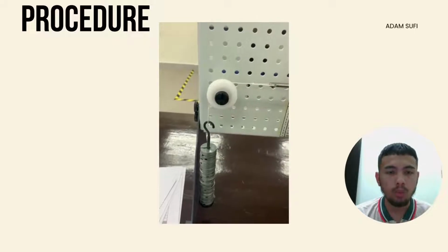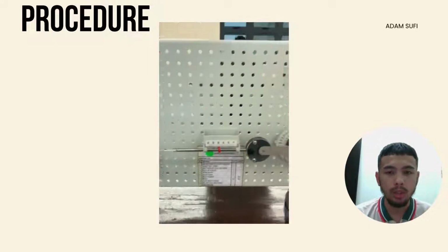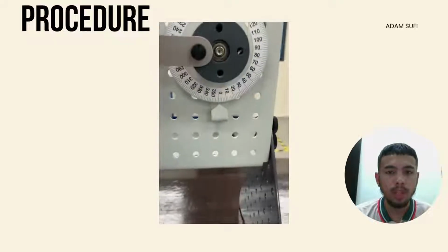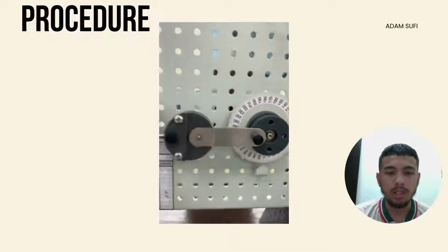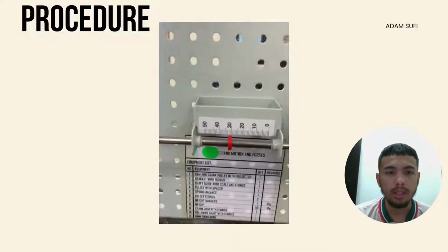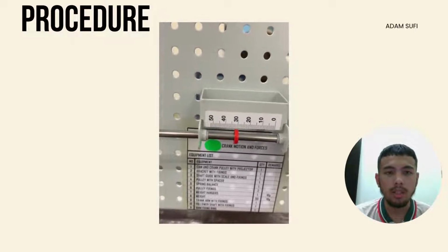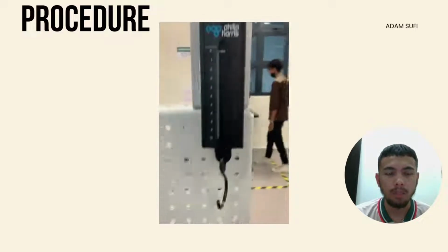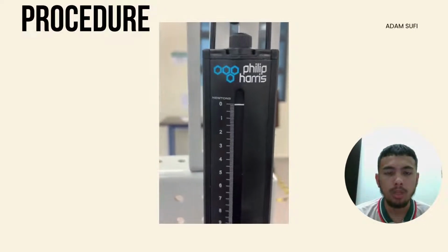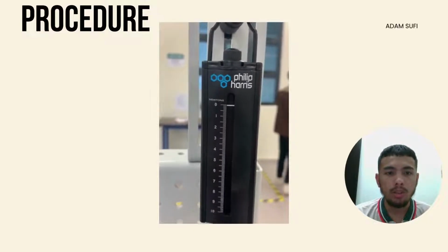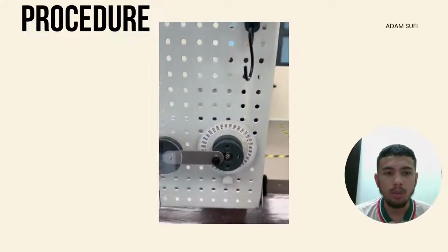So for the procedure, we need to place a mass of 500 gram on the slider load. The weight on the hook will pull the crank out flat, to the position generally called dead center, which is the angle equal to 0. Then set the indicator start at scale 30 mm. After that, hang the spring balance with adjustable hook. Ensure the value of spring balance is 0.